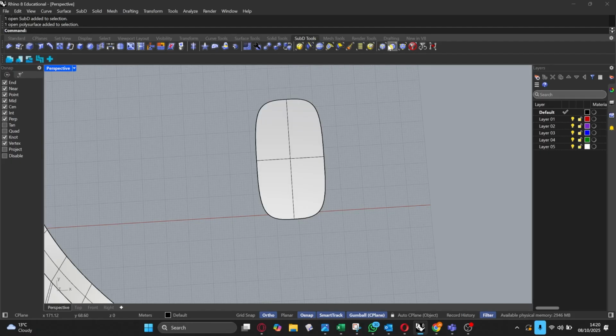So if I was going to try and create the same type of geometry, if I wanted to create it here, I'm going to use these, our filters here. And what these do is if I click on my filters just down here, and yours might be a little bit further down in Rhino. If I turn these on and select them, can you see what's happening to my filters just here? What it does is if I click on edges, it's going to turn everything off apart from edges.